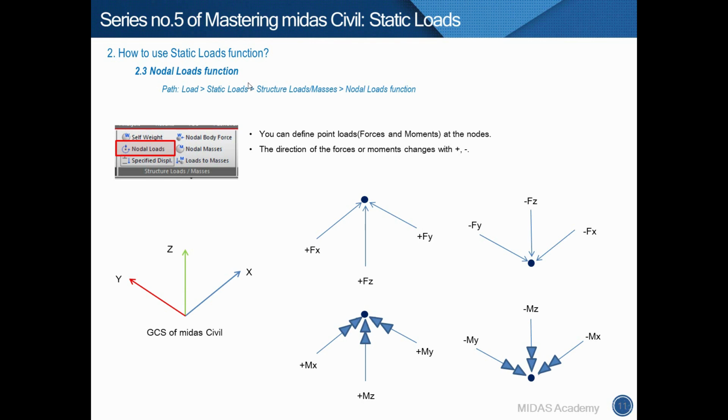Next one is nodal load function. This function applies point loads to nodes of elements. Available load types are actual forces and moments. The direction of loads follows global coordinate system.